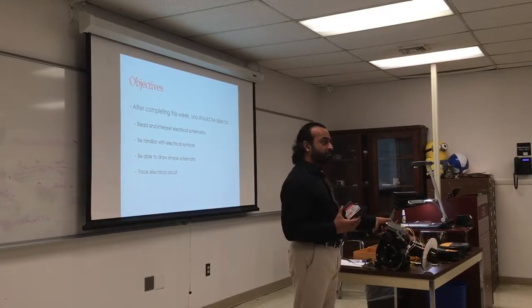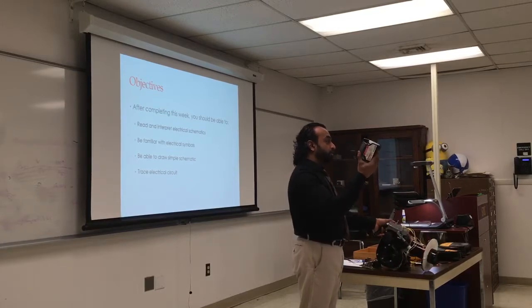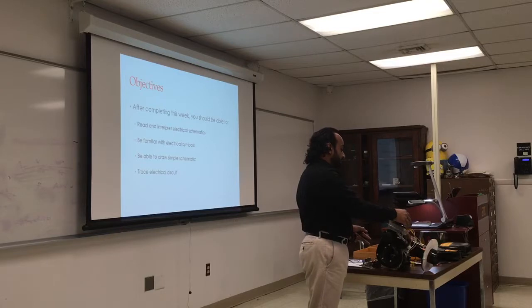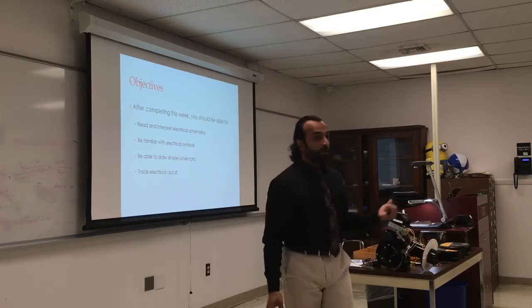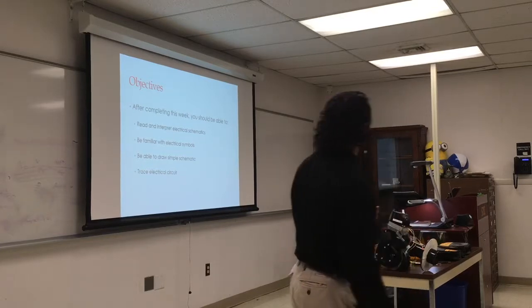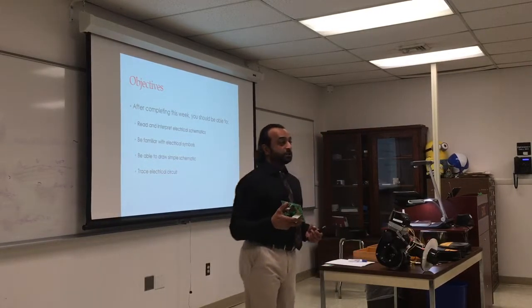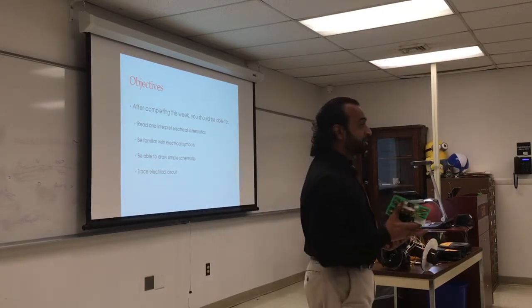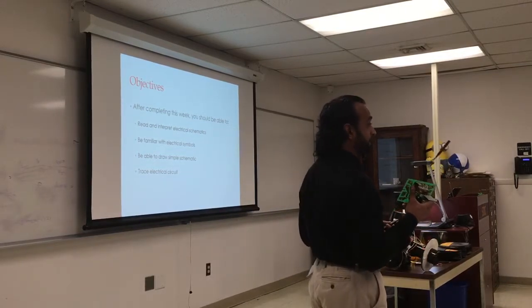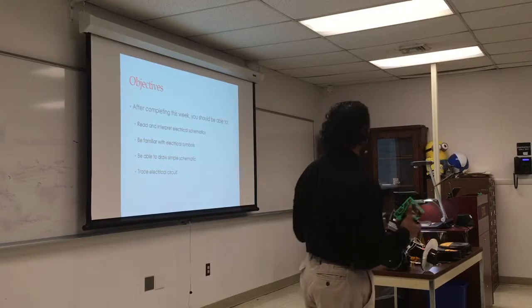These can convert to gas or oil, and this controls all the mechanical components in the oil burner. So how does it connect? And what is this control? Water temperature. It's kind of like a thermostat, but for water. That's why they call it aquastat.